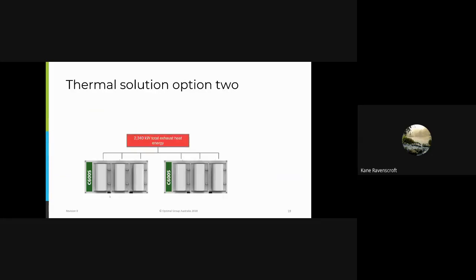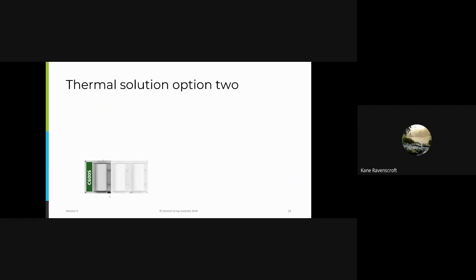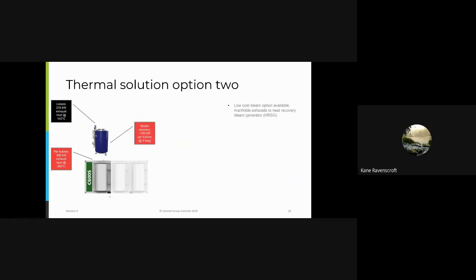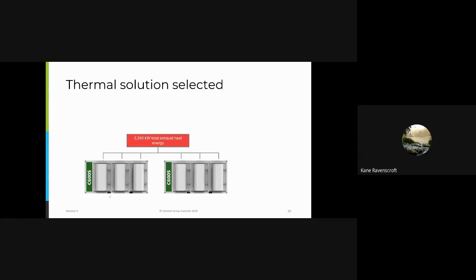So the second solution was to look at a low-cost steam option, which we have, where we can put a steam recovery unit on top of the unit that gives us about 180 kilowatts, but the losses are much higher. So we're only getting about 45% of the available heat recoverable as steam. So not a great outcome. It stacks up today, but as we said, if gas prices continue to rise or something else was to change, then that would certainly put some pain onto the business case.